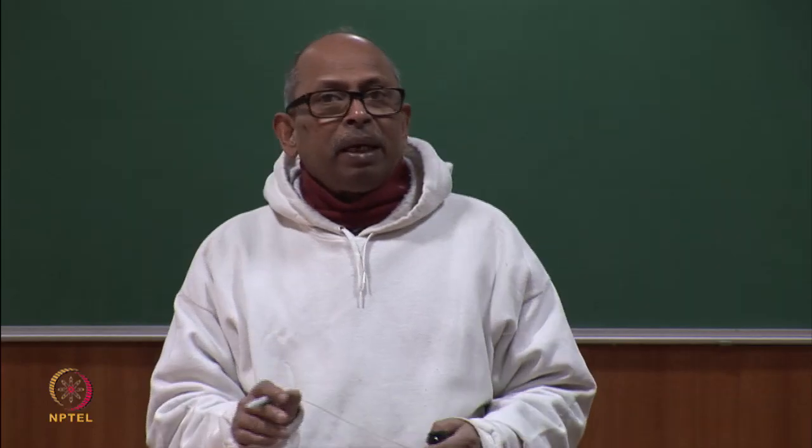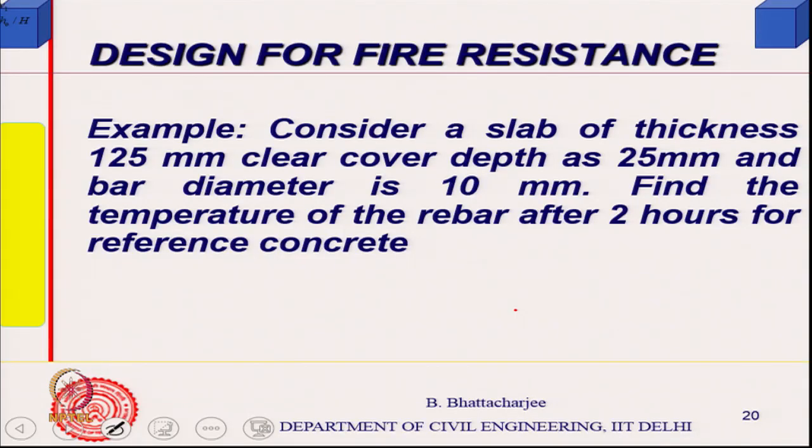So, just as an example, like we did for steel, let us do it for a slab, a simple case. The thickness of the slab is 125 mm, the cover depth is 25 mm and the bar diameter is 10 mm. Find the temperature of the rebar after 2 hours for reference concrete. So, I just made it simple.